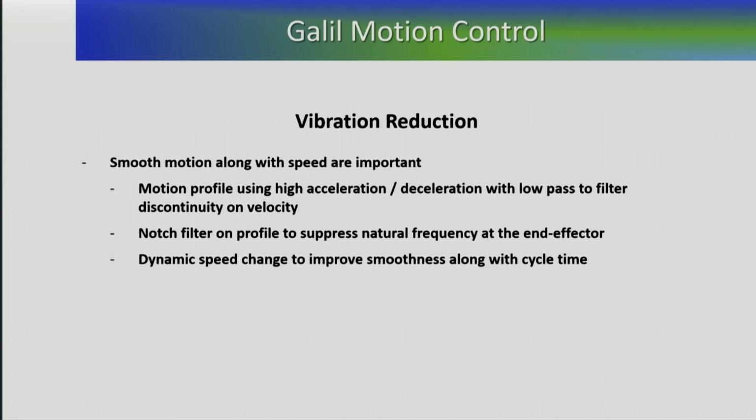Well, how do you characterize the vibration and eliminate it? The very first thing is you bring in the equipment or instruments to characterize that vibration. If the vibrations are seen by the motor, it is a lot easier because you can then read your feedback sensors and it tells you what the vibrations are.